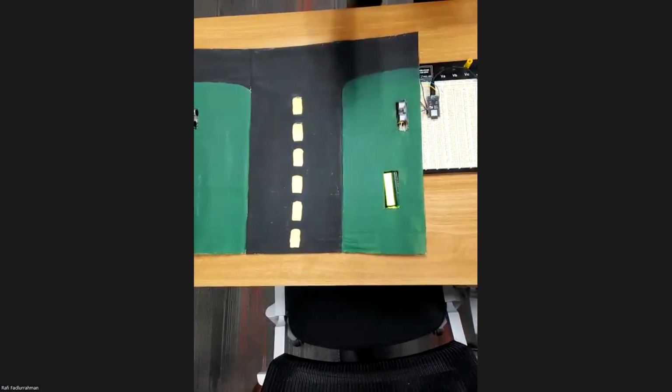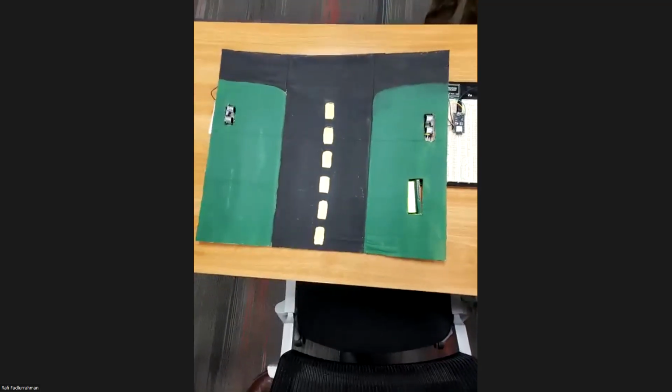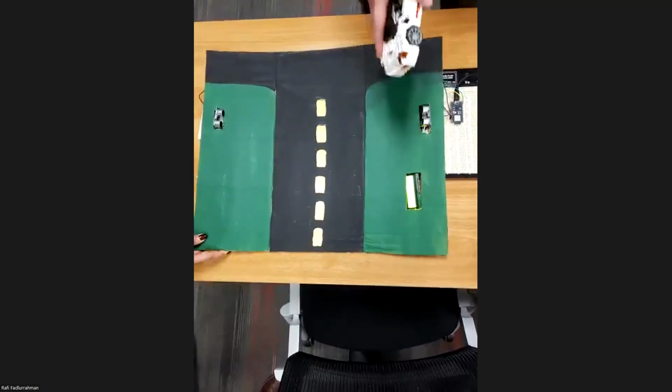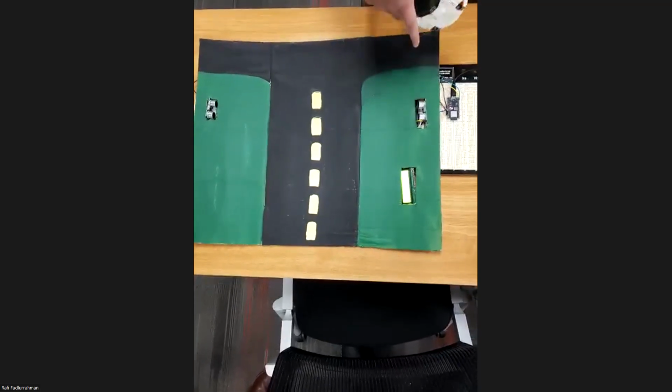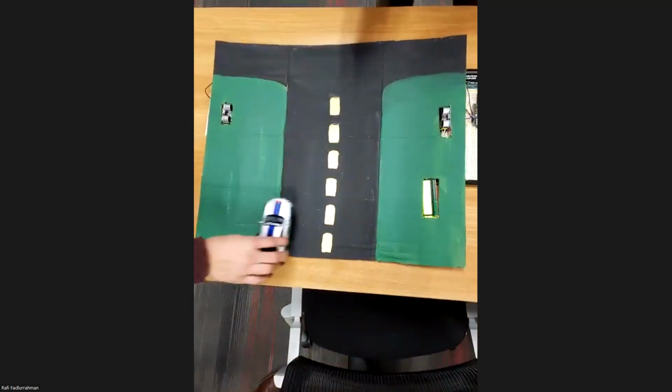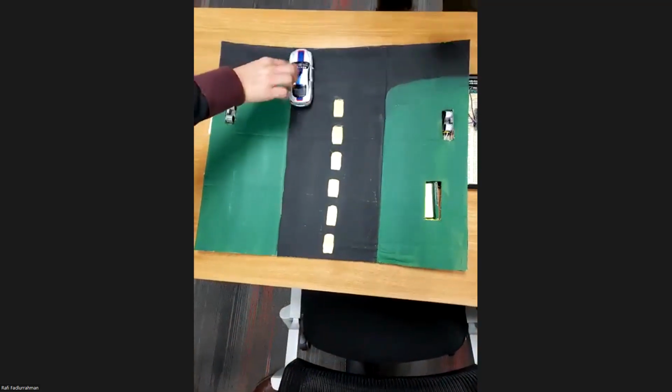There's also a refresh delay. That's one of the things that we had to play around with because of the reliability of these. If you set the delay too high and you read in a bunch of values, it'll sometimes say that it's less than the max range and then it'll detect an object. So, one of the downfalls of the $5 sensor.